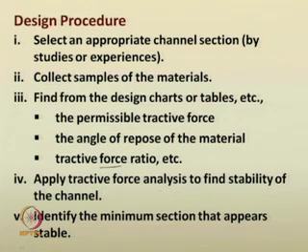Now, apply the tractive force analysis to find the stability of the channel. After determining the tractive force ratio, identify the tractive forces at each location, and find the corresponding discharge from the channel. You see whether that corresponding discharge obeys the capacity discharge required for the channel or not, and you can suggest that. So, identify the minimum section that appears stable.